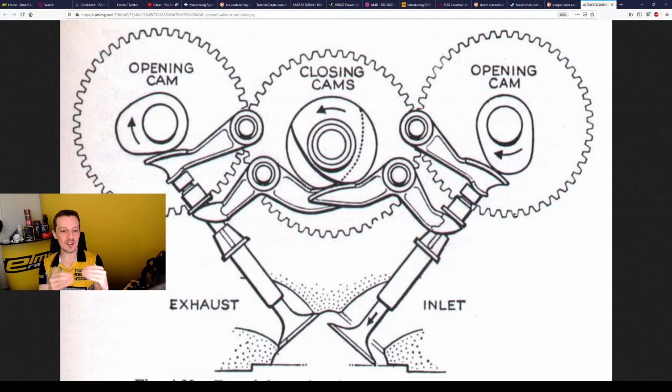So this has inertia, and it depends on where the force is that you're producing. So this is, for instance, a very good setup that will not have a lot of vibration. You have a contact point that is almost directly above the valve that you're transmitting that force to. So there's only a compressive force between a solid piece of metal, or whatever material you want to use.